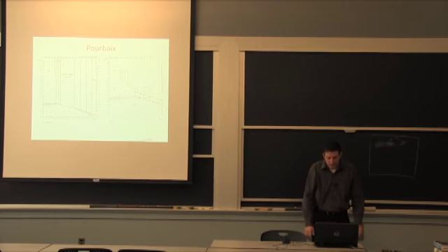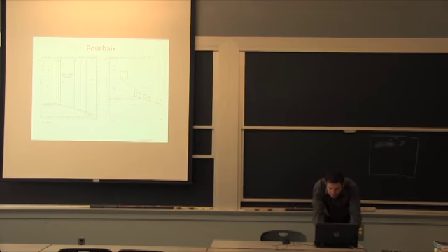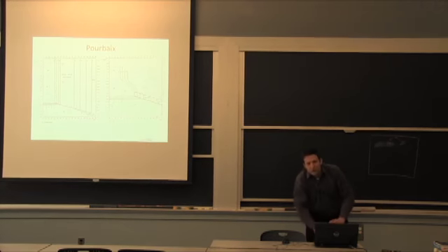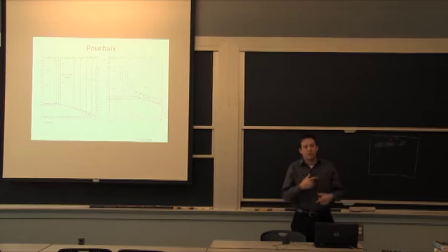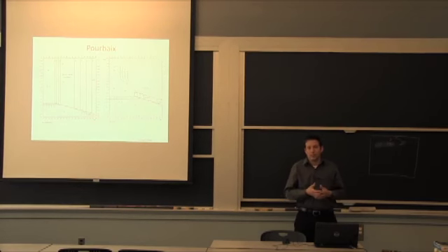With regular steel, let's do steel first. We're going to look at the Pourbaix diagram, and the idea here is to look at the potential applied to the metal as a function of pH and see which phase of the alloy wants to be favored in terms of equilibrium, in terms of thermodynamics.